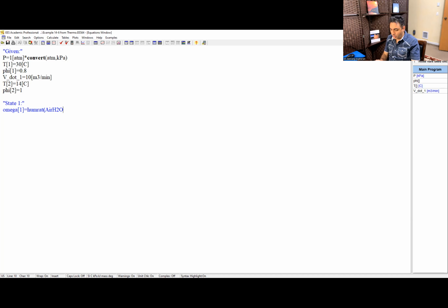Okay, cool. And you need 3 properties. One of those properties is always pressure. That's very important. That's why I told you, if you go to Colorado, the pressure changes, then you're going to change this pressure, and that gives you the correct psychrometric values for that particular pressure. The pressure that we have in this problem is 1 atmosphere. All right, P is P.